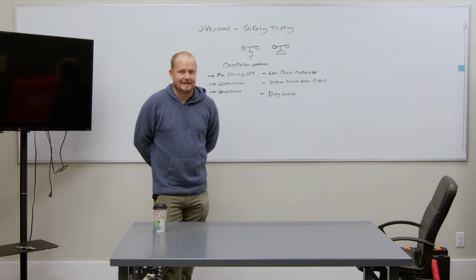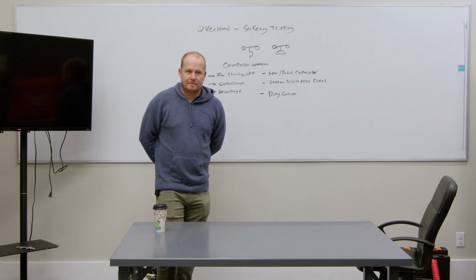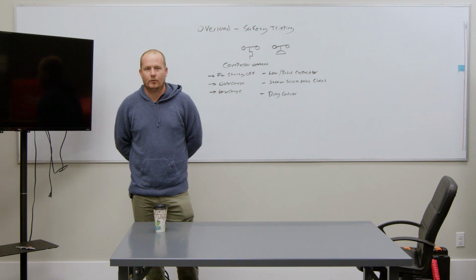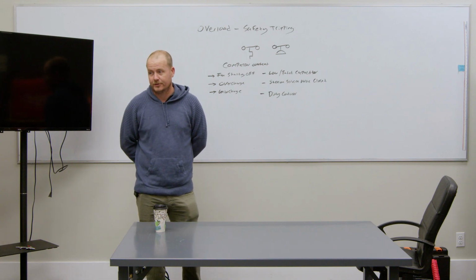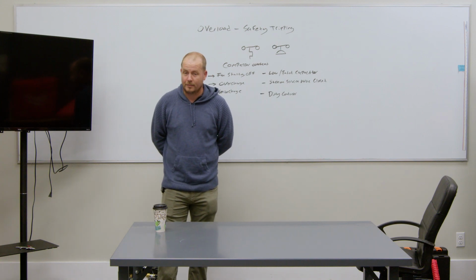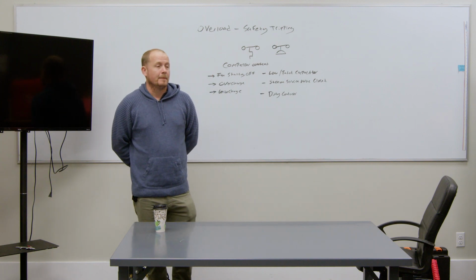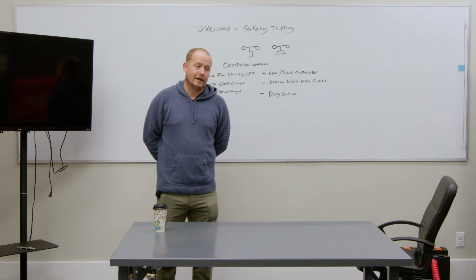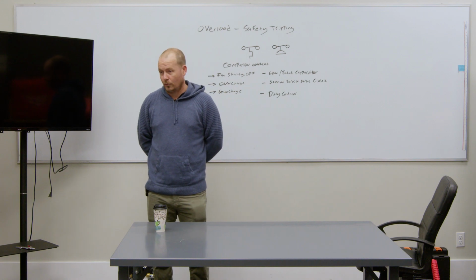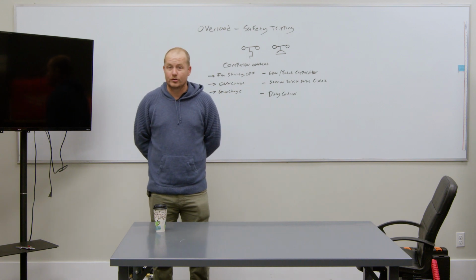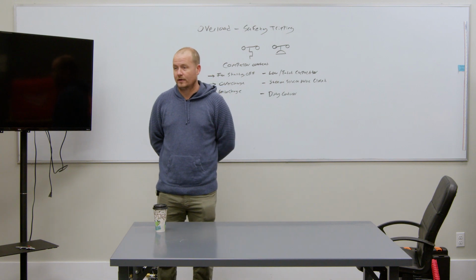All right. So the point is that what you don't blame is the pressure switch, because that's what people would tend to do. They'd say, oh, something's wrong with this pressure switch. So bypassing it, that would be an obvious no-no, which some technicians would do. None of you, I'm sure. You don't bypass safeties, right? But the other would be, okay, there's probably something wrong with the safety switch, and then once you replace that and it does it again, oh, it's probably the board. But it usually isn't the safety switch or the board in intermittent problems like this.